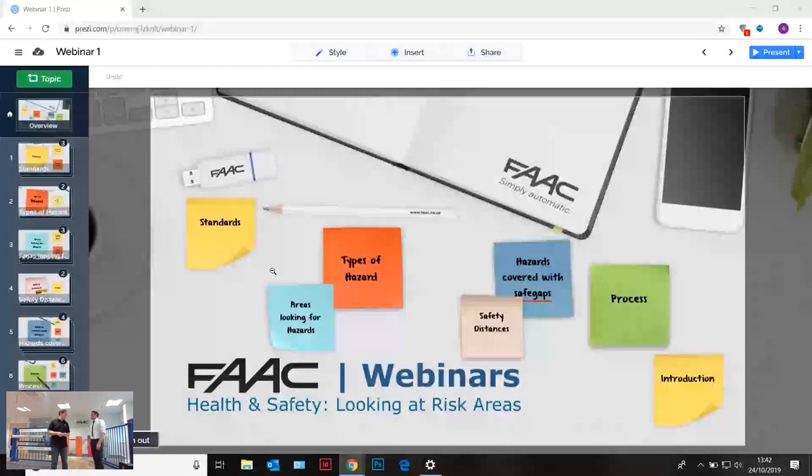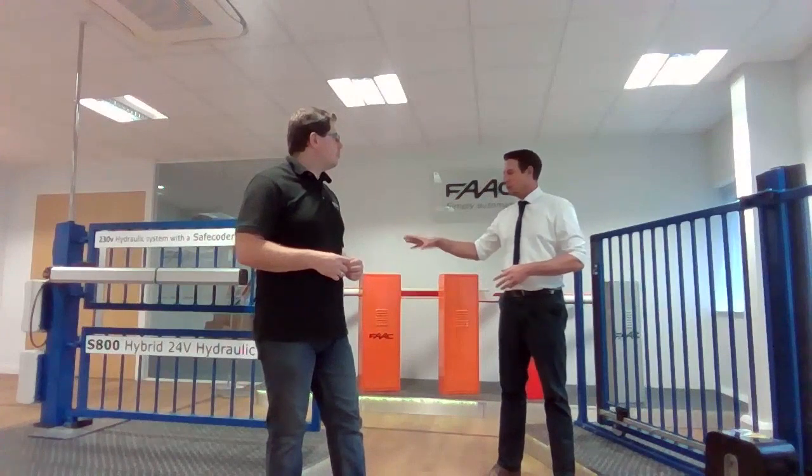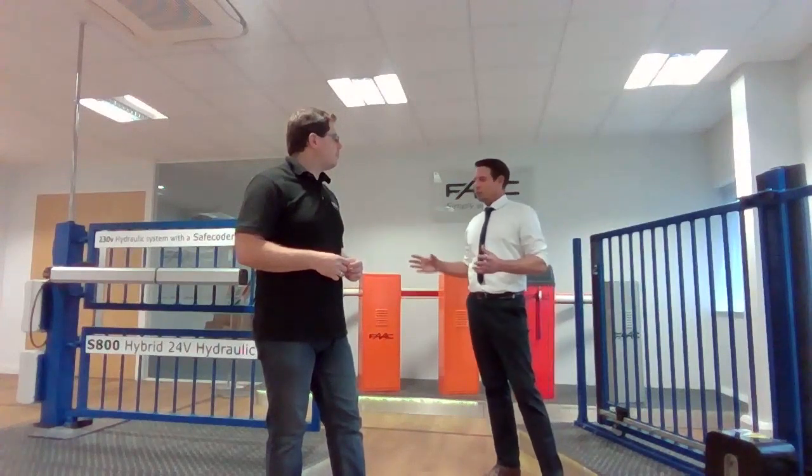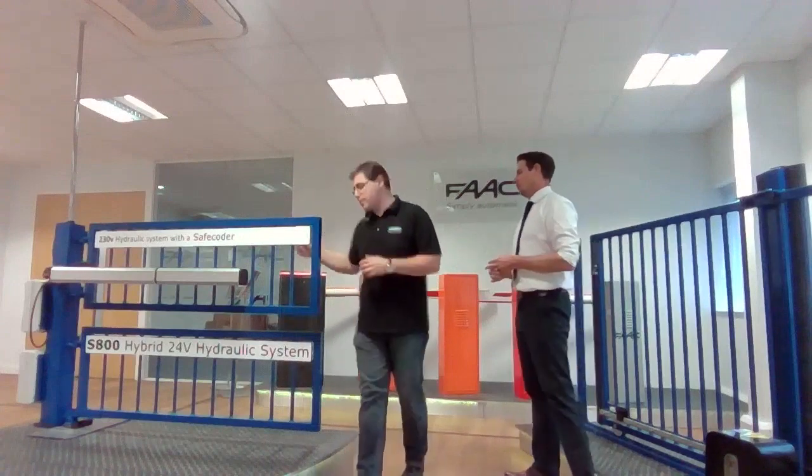I think when they talk about bracing, and this is probably one of the most common questions I get asked recently because it's been upgraded within the DHF documentation and such, it's all regarding the actual safety of the gate. Where it's not braced, it can break the hinges, fall off, and how do you get around it? Yeah, that's all it essentially is. It's just making it more clear to people that that's how it's supposed to be. We're looking at essentially the hinge positions.